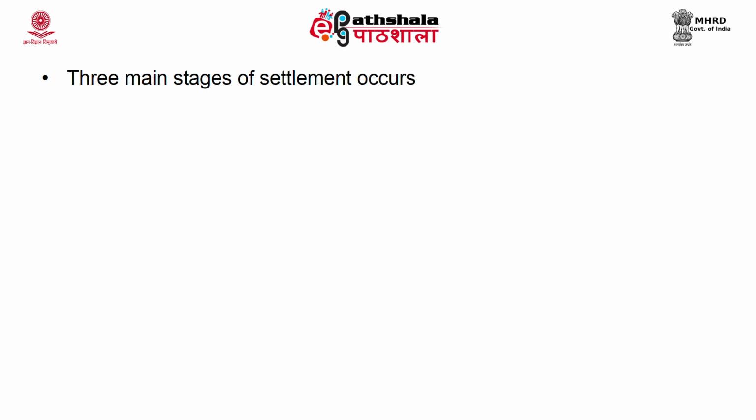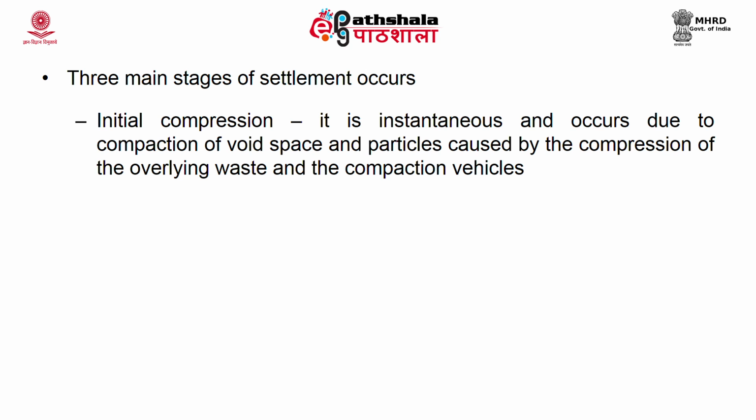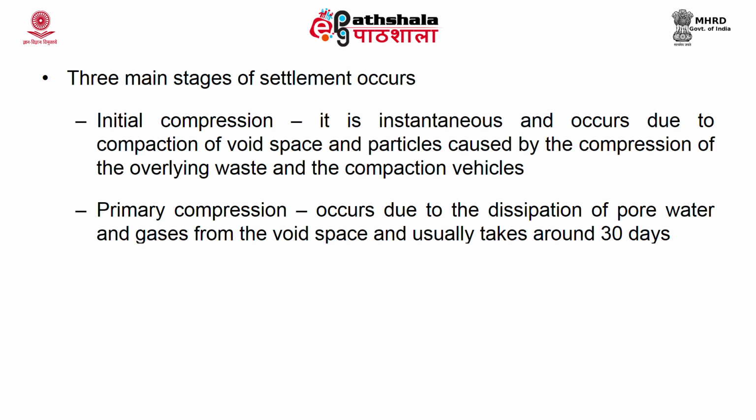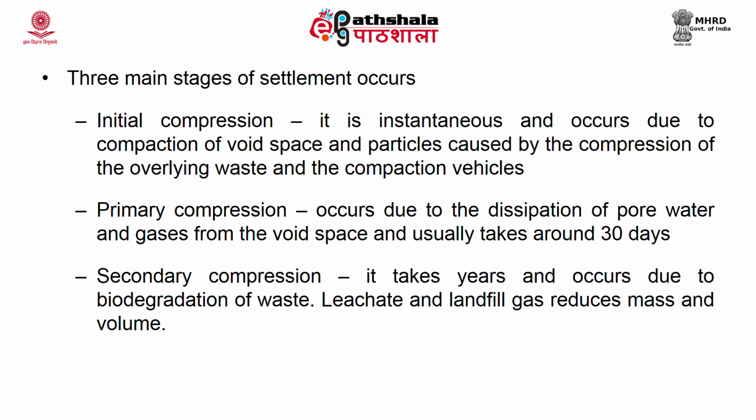Now, there are three main stages of settlement. One is your initial compression, second is primary compression and third one is secondary compression. Now, initial compression is instantaneous, that is spontaneous, and it occurs due to compaction of void space. Any material, you cannot say it is tightly packed, it can be loosely arranged.